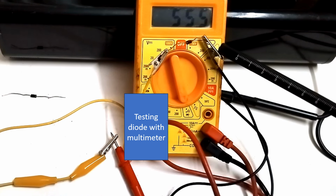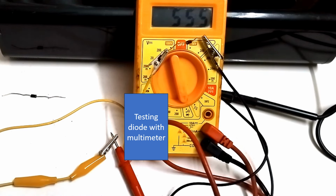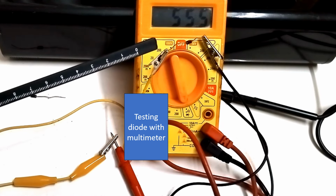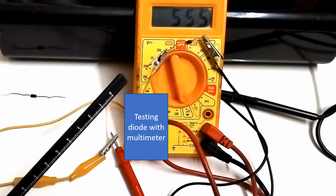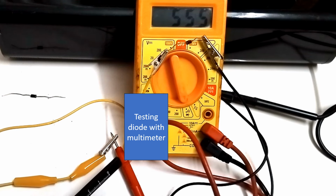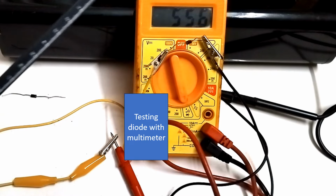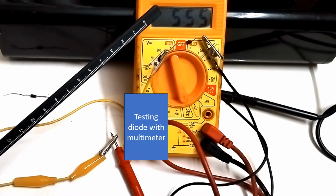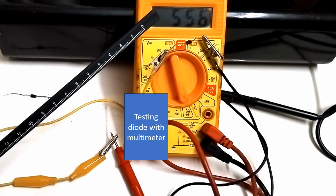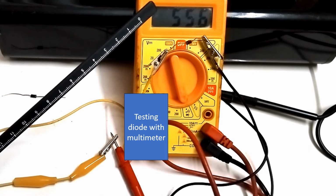And then the black lead is connected to the cathode and the red lead is connected to the anode. Here I am using a yellow cable with crocodile clips on either side to connect from the red lead to the anode, and you can see the display here, 555, that is actually 0.555 volts or 555 millivolts, that is being shown here. Now we will reverse the connection and see.